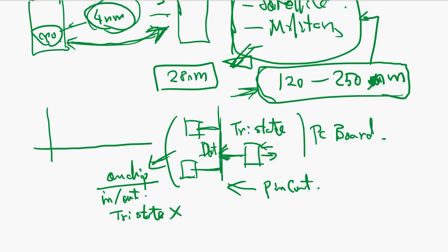If you make a bus like that on chip, typically the bus has a lot of capacitance, and it becomes a rise time issue. We want nice ramping up high and nice going down low, and instead it becomes like this. This is definitely an issue internally.